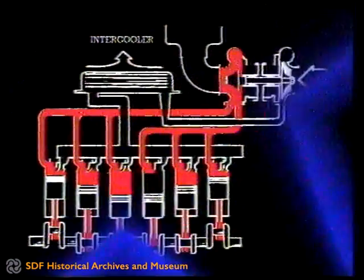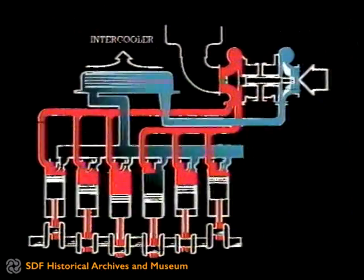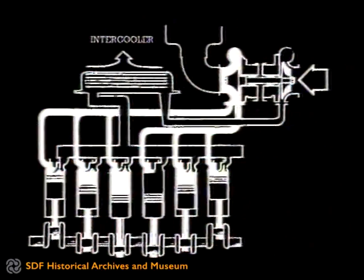What is the intercooler? During compression, the air, besides increasing its pressure and its density, heats up. Its density, and hence the power generated by the engine, would be greater if the air were not heated up. This penalizing situation is felt particularly in cases of forced turbocharging, 1 bar and beyond.